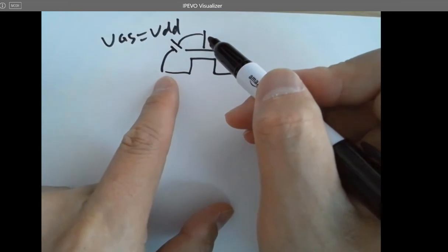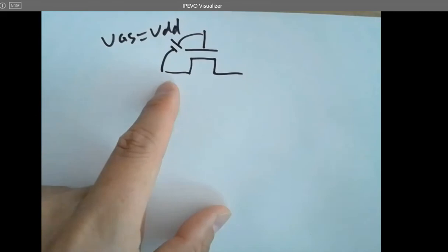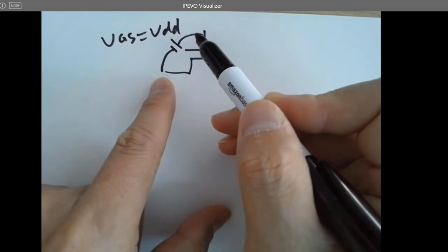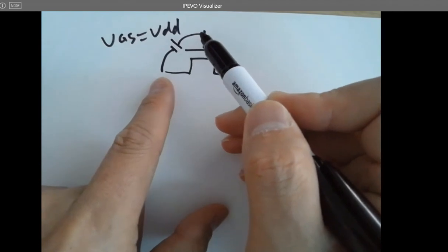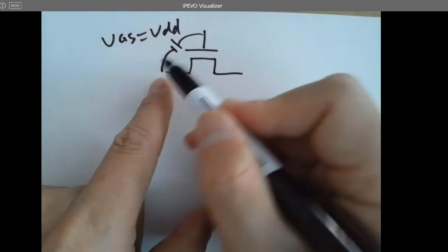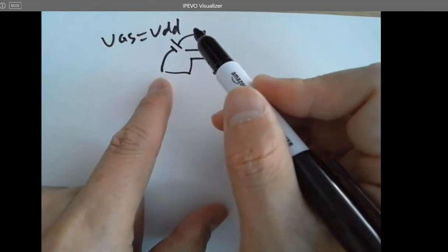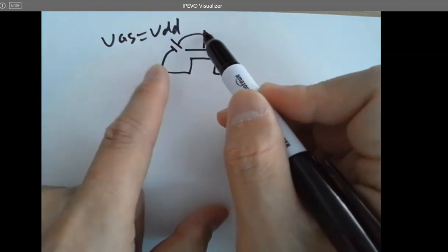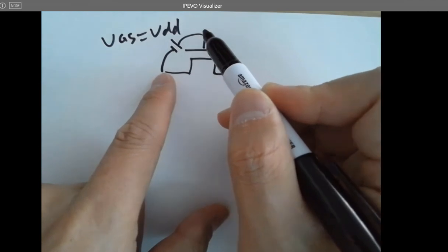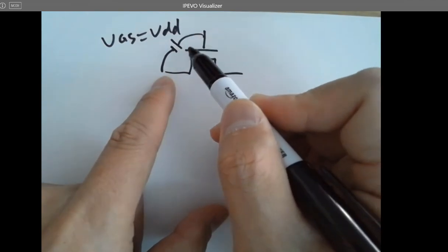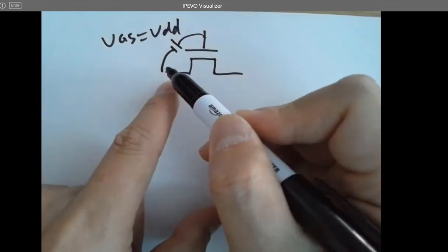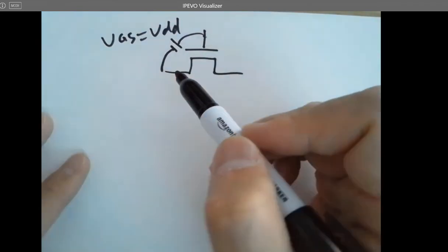No, it's constantly VDD because it's a source, it's a super strong source. Whenever there's a little difference over there, like AC or noise or anything else, it will be compensated or canceled by the source. Since the source is gonna give you a constant DC voltage over these two terminals, and it will be exactly VDD over the G and S terminals. Right, this is the ideal case.